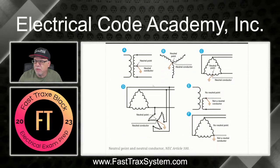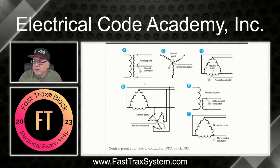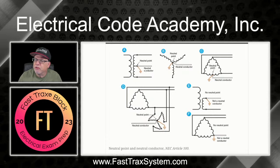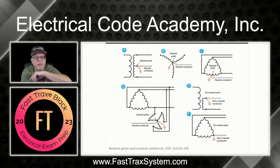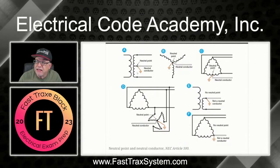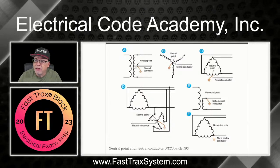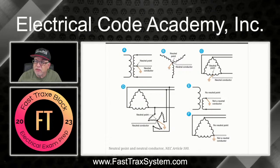All right, so let's look at what we've got here, each one. The first one is an example of a single winding. This would be a 120/240 volt single phase, single winding where it's tapped at the midpoint. From phase to phase on this winding is 240, but from phase to center tap is 120.